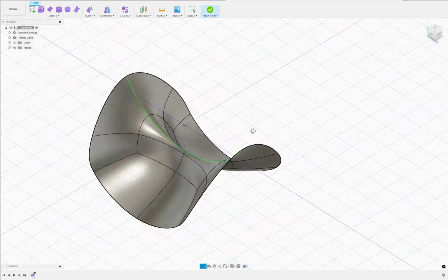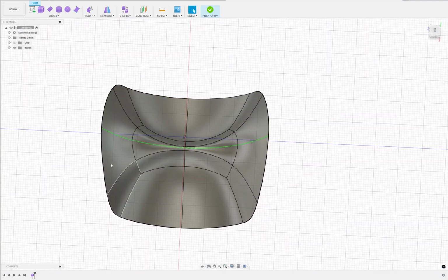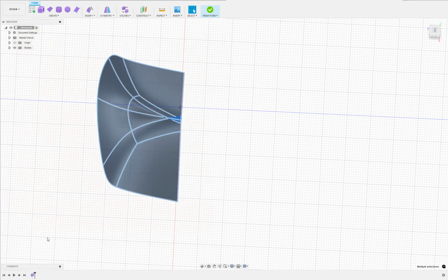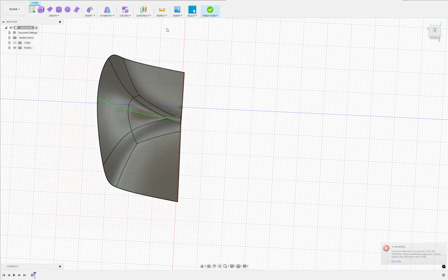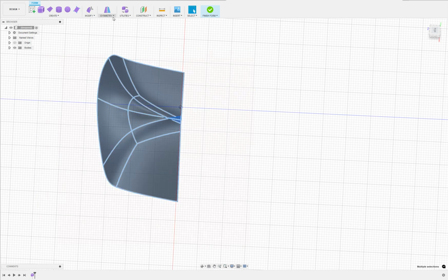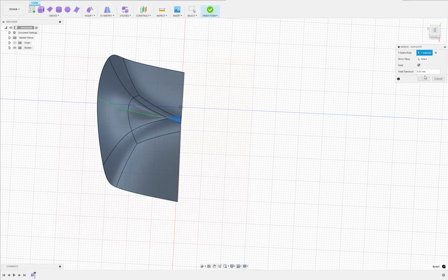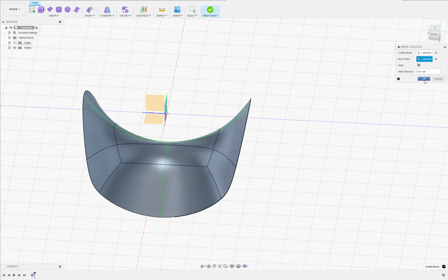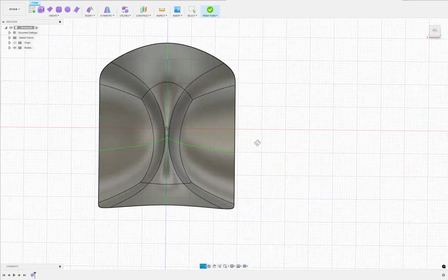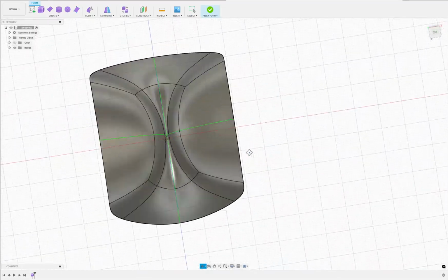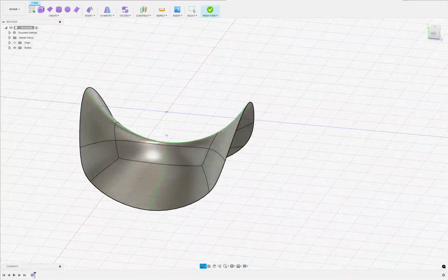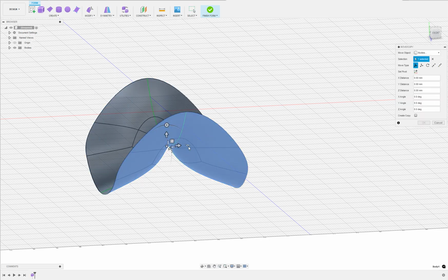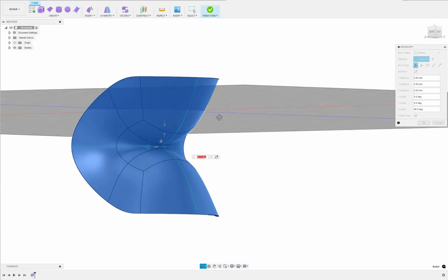We're good, but you know, it's only like one symmetry axis, but it's actually symmetric in both axes. So we can just, again, delete that half. Again, symmetry, but that's not the right one. Symmetry, duplicate, the mirror plane now is this one, right? And weld this on. And now we have both axes of symmetry. And of course now the orientation is wrong, but that's not a big deal because for this we have modify and move copy. And here we can just do that.